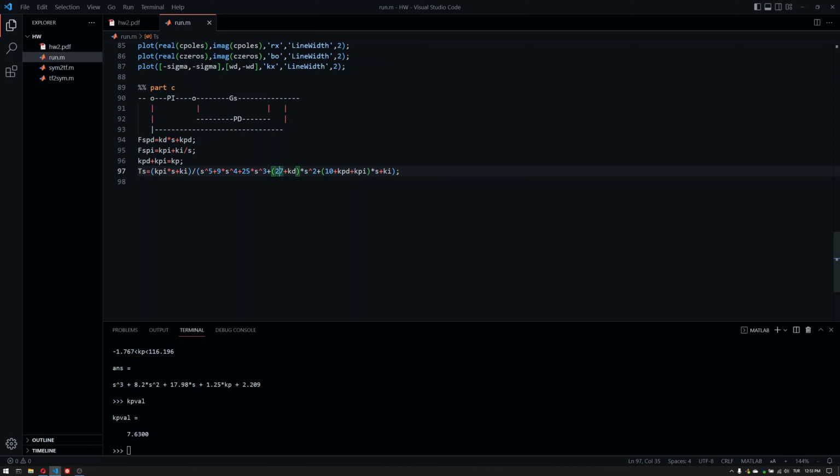Since the PID parameters are in the same place as they should be in the PID structure, we will get the same pole assignment here. So we will get the same closed loop poles. And we got rid of the zeros of the PID controller. We have a zero that is placed manually, so everything should be better than it was. So, based upon this fact, let me just comment this out. I'm not going to redesign anything.